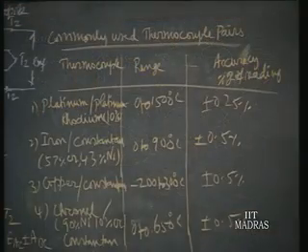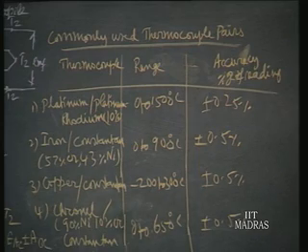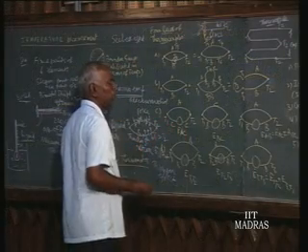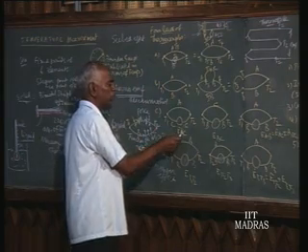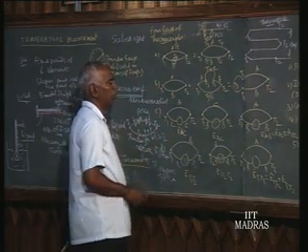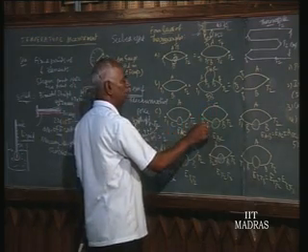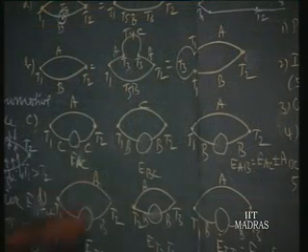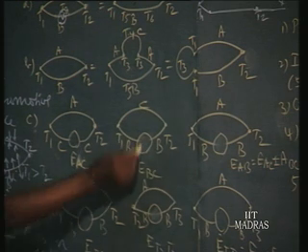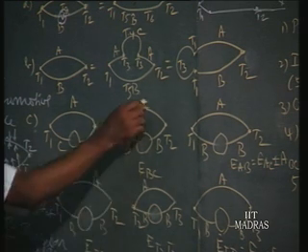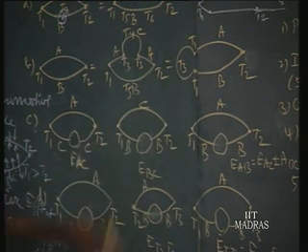That is what is explained as the third law. First, you find the thermocouple is made up of material A and C, and the voltage EMF developed is EAC, if you call. Similarly, if you have material C and material B with the same temperatures T1, T2, hot junction, cold junction temperature, and if you call the thermal EMF as EBC, the C material is common in both, that is the same as platinum.